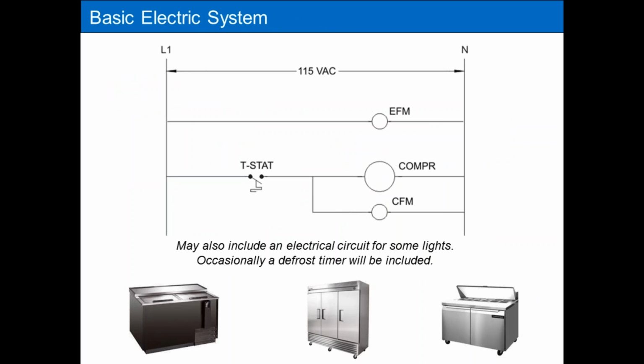The electrical side of these systems is also equally simplistic. There's not a whole lot to how they are electrically put together. But there are some important things that you should know going into troubleshooting these coolers from an electrical point of view that will help you out. One thing is the evaporator fan motor is designed to run all the time. It does not cycle on and off.